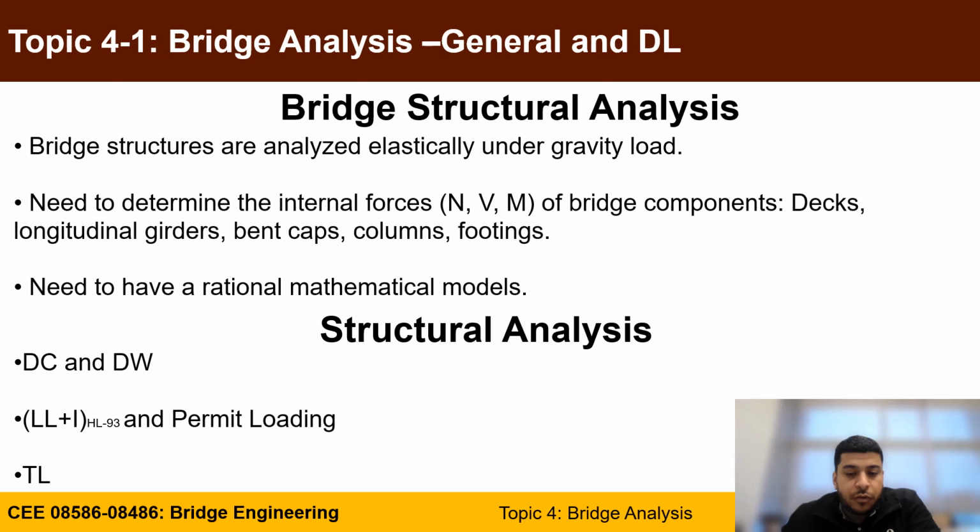As we mentioned before in the bridge loading, we have trucks and moving loads, which are very much not common in building. But in bridges, in order to do your bridge structure analysis, you have to assume that the bridge, which is a fair assumption, will behave elastically under gravity load. So no cracking, no sign of yielding, etc.